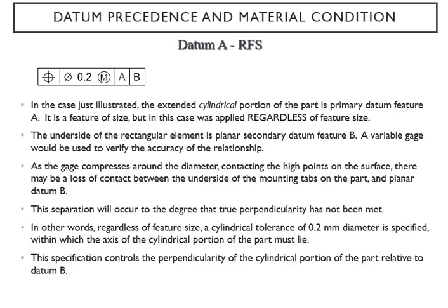Okay, and here is your control frame. We're just reiterating the same thing, where you can get the cylindricity because of this symbol right there. Make sure you study all your symbols so you know which one is what. The cylindrical portion of that part is going to be controlled by the primary datum and then the secondary datum right there, regardless of your feature size.